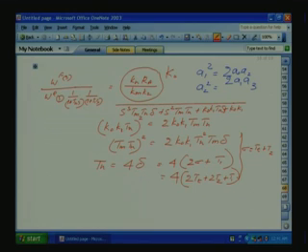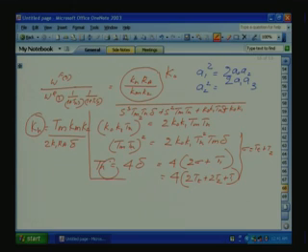Then, substituting this one, finally our Kn, that is our PI controller P gain, Kn will be Tm Km K2 divided by 2 K1 Ra delta. This will be the Kn. So, we got Kn and Tn from the optimization.